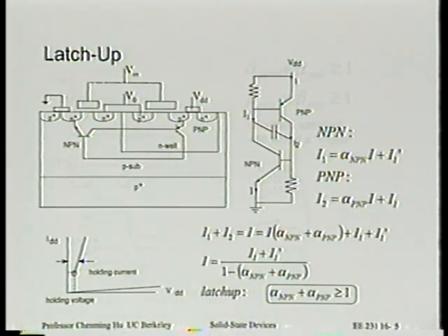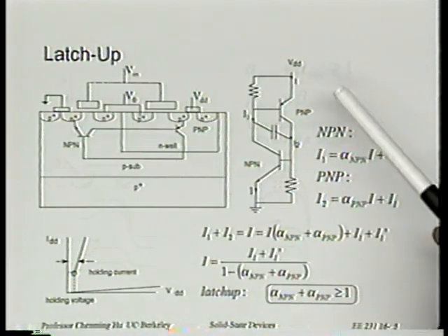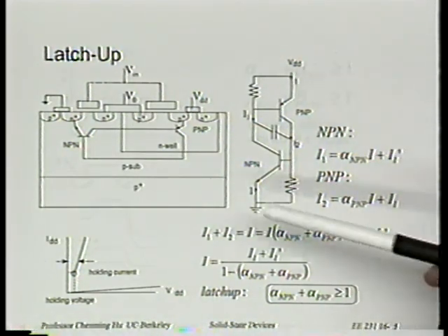All right. And now, of course, we understand what's going on, and we know when things may go into latchup. That's when there's some particular trigger, and I'll just leave that word trigger there for a while. We'll come back to talk about it. So let's just quickly explain why a CMOS circuit sometimes can appear to be a short circuit between VDD and VSS.